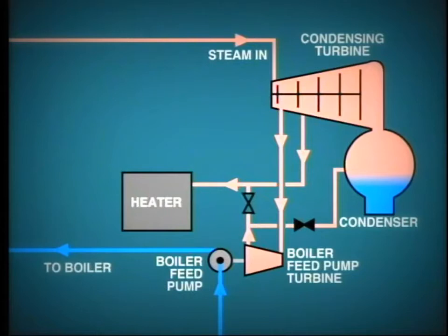The discharge from the turbine drive may then be piped to a lower point of extraction for further heat utilization. Alternatively, it may be piped to the condenser so that the condensate may be recovered even if the latent heat is lost to the cooling water.